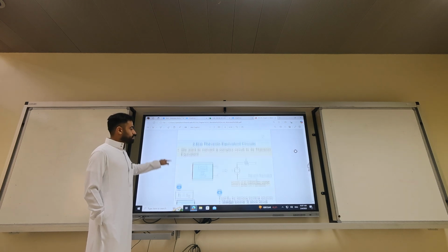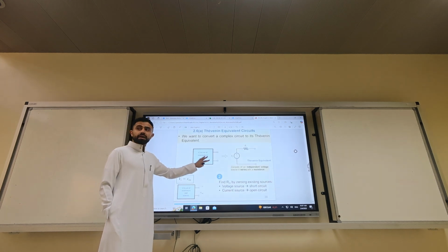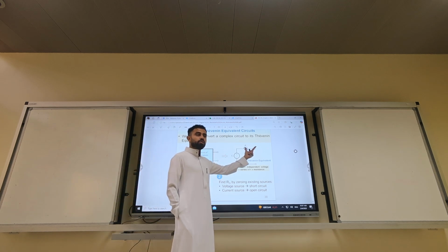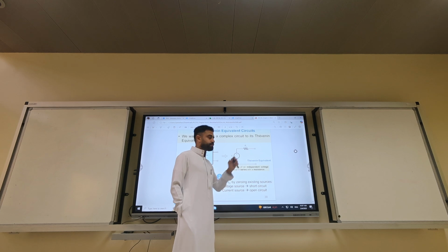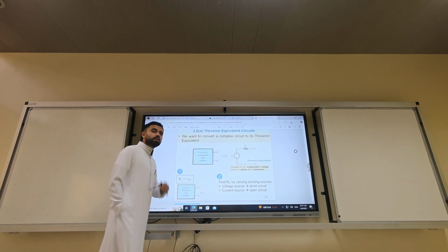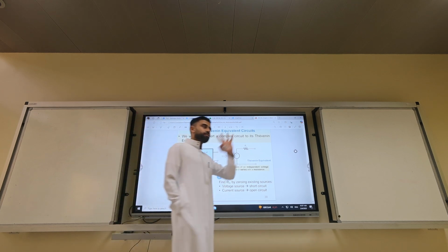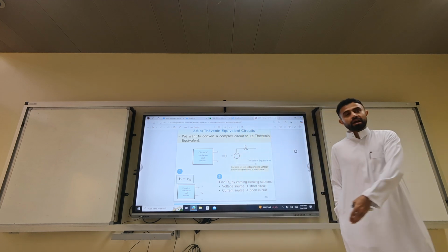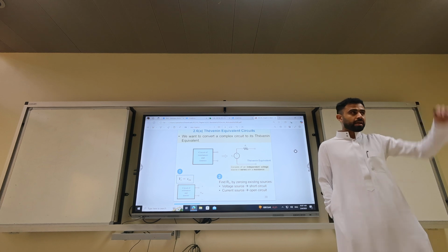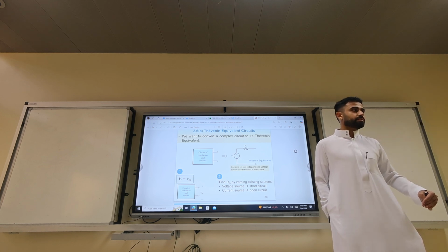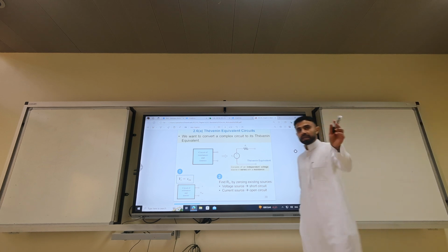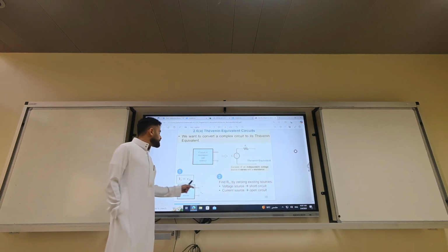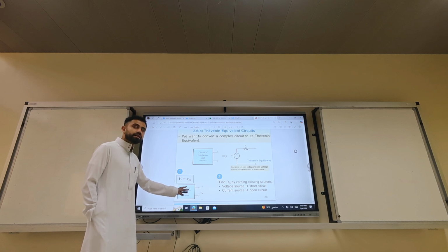So let's review them. We said if you have a spaghetti circuit, you replace it with a voltage source and a resistor. We call them R Thevenin and V Thevenin. And how to find them? What did I tell you? You have to first find R Thevenin to save time in the exam. In case you fail to calculate V open circuit, you eliminate choices. That's a technique, okay? Then you find V open circuit.